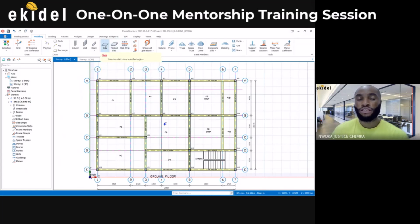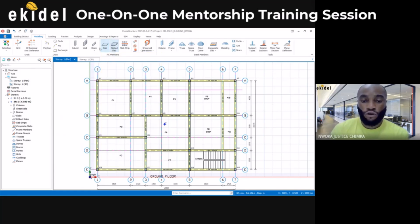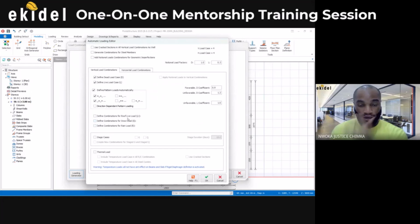Now, before you insert the concrete slab, you'll be asked to define loading combinations and all that. So if I click on the concrete slab now, they will ask me a question, load case must be defined and all that. I'll say yes, define the load case. Now, once you have come to this load combination dialog box, you then come here that says loading generator. I'll click on this generator, and then you will see vertical loading combination and what?